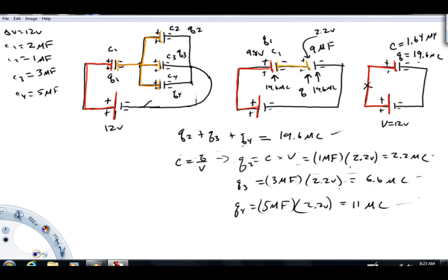And in the picture in the middle, that means that 1 coulomb moves through here, 1 has to move through here, here, here, all points in the circuit. And what that tells us is that the charge on those capacitors has to be the same. Right, so those capacitors carry the same charge, but not the same voltage. So it's pretty easy to find the voltages using this once you know the charges.